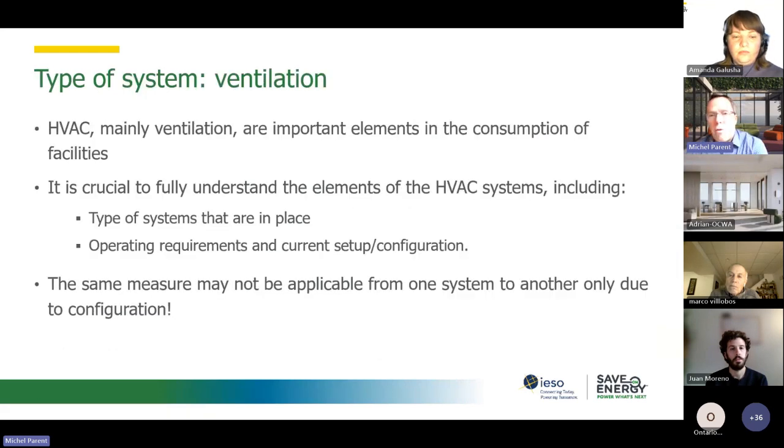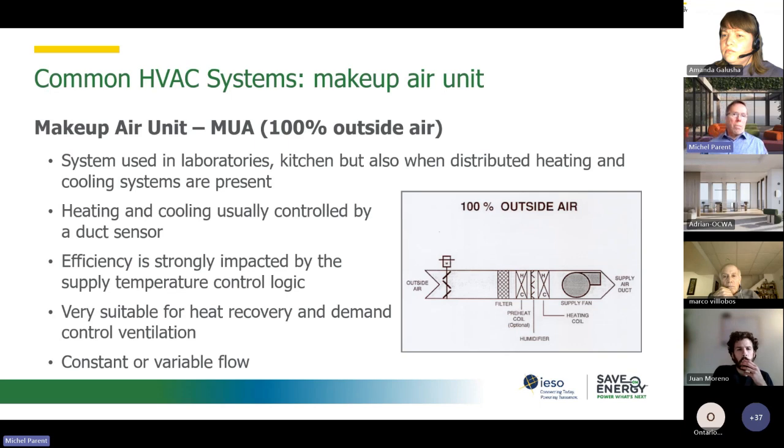And this one is actually for HVAC quite critical, the type of system. It might seem very trivial to say, hey, we know what type of systems we have. We have a makeup air unit, and here we've got an air handling unit. But people often make critical mistakes in properly identifying their HVAC system. Just so that we're on the same page, I'm going to go through a few systems just to tell you which you need to be very careful about. It will have drastic impact on some of your energy saving measures in task step 3 and possibly step 4.